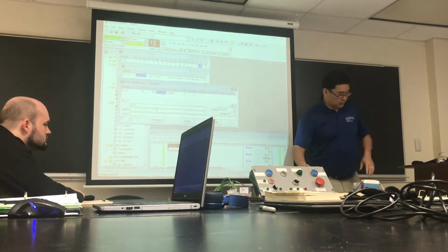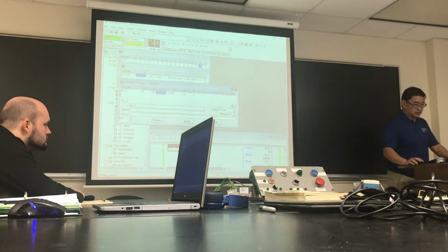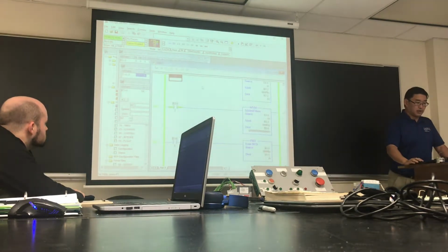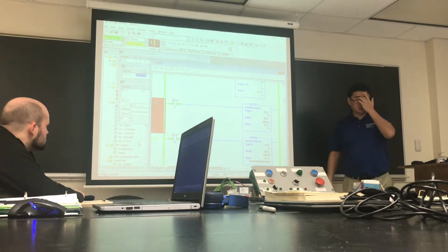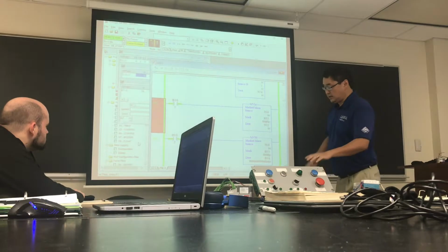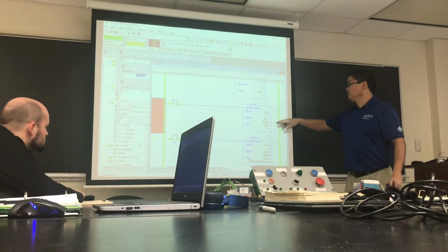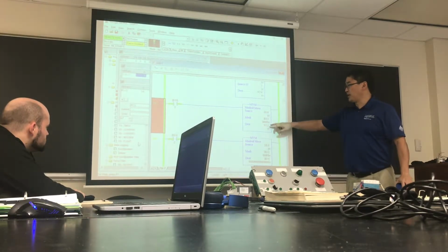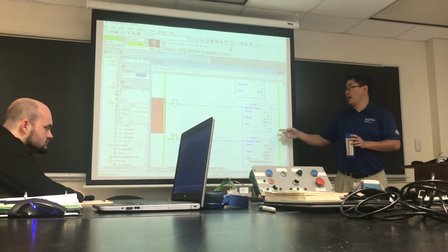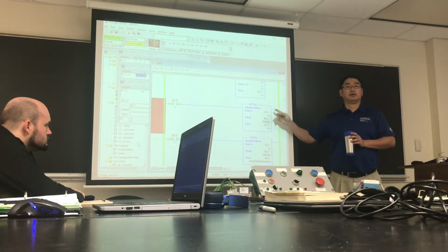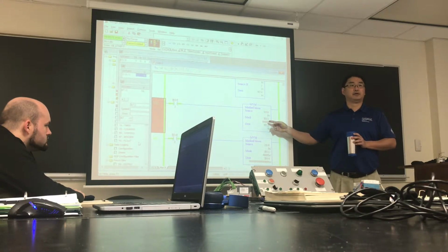And so as far as the number of rungs, really the only rung you need is this guy, because he's moving it from the input table through the mask straight into N7. I don't actually even need the from BCD, the FRD instruction, do I?